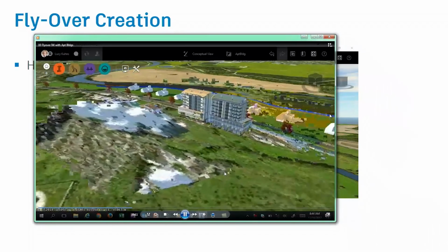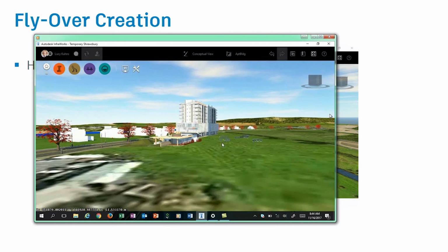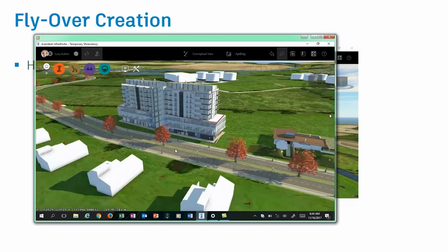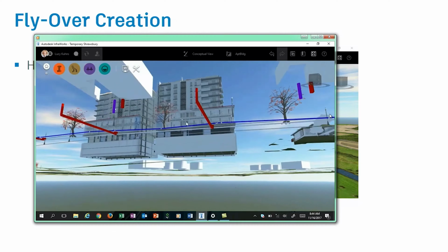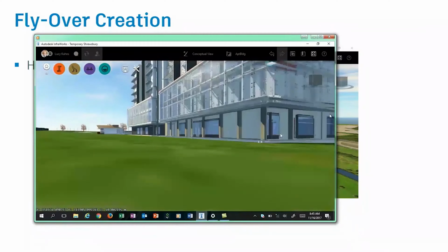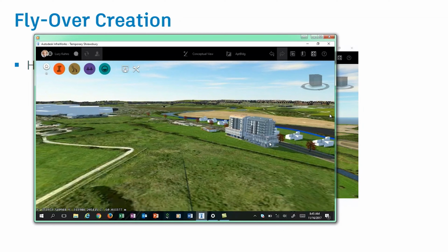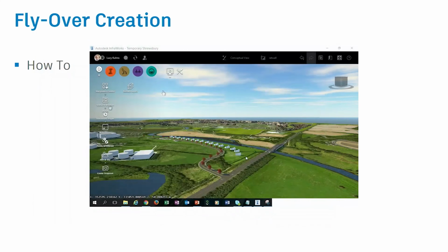So if you take our data set and put it all together, 1, 2, 3, then you'll end up with something that's simple, but it gets the point across. These objects, if you set up the base coordinate system in Revit, the survey point correctly, you literally can drag and drop the Revit files into the InfraWorks canvas. We know we can do that with shape files and other content, but I bet you didn't know that you can drag and drop Revit in. You still need to configure it, but you can drag and drop it.